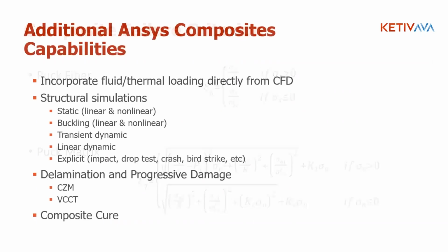Okay, so once you define the composite material in Ansys, you can use it just like any other regular element in Ansys. You can combine it with the loadings from CFD, and it just becomes a regular finite element analysis.